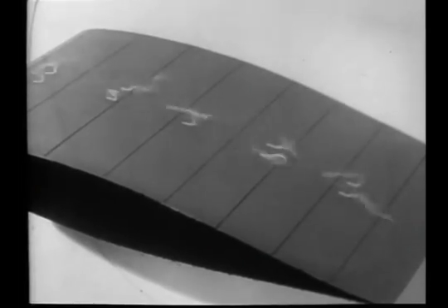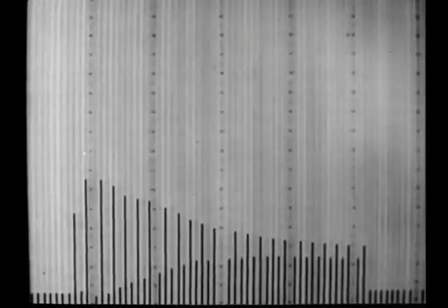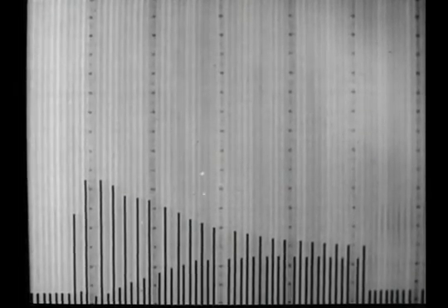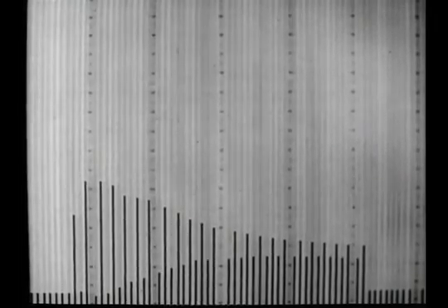This is also reflected in the pressure distribution. When stalled, this profile suffers a loss of lift. As suction is applied, lift is restored. As the flow is reattached, the pressure distribution approaches that of an inviscid flow. The irregularities in this pattern occur where the pressure taps are located near the suction slots.